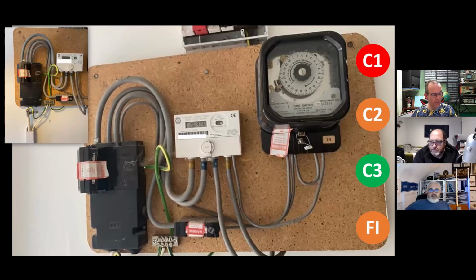So, what do we think? And what do we code? It's a cracking one. Yeah, those time switches, the actual thin wire that comes out, the fifth one to the meter, is actually a switched neutral, just to be controversial there. So it switches on that onto the neutral to switch the other rate, and if it's not connected, then it's on the primary rate.